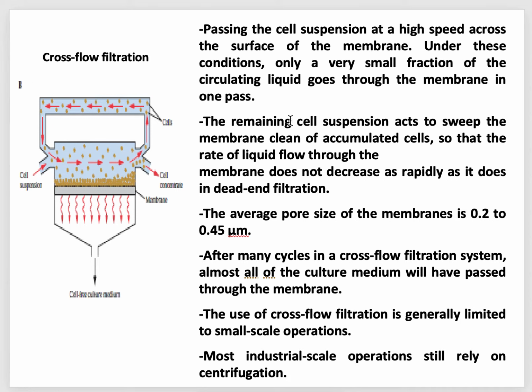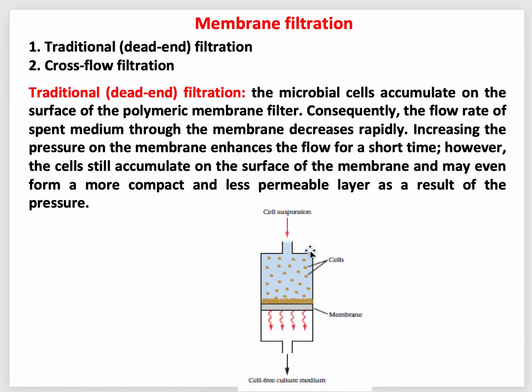Due to the force that this circulation of the liquid creates, they sweep away some of the deposited cells from here. So that's why this kind of filter doesn't get clogged as rapidly as the traditional dead-end type filtration.